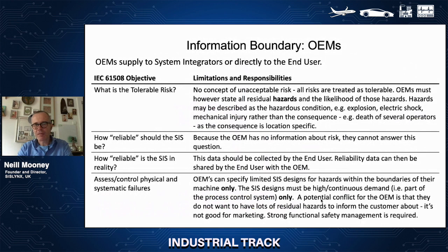An information boundary for an OEM. OEMs supply to system integrators or directly to end users. In terms of tolerable risk, there is no concept of unacceptable risk in the standards. All risks are treated as tolerable. OEMs must, however, state all residual hazards and the likelihood of those hazards. They can be described as the hazardous condition, e.g. explosion, electric shock, rather than a consequence, i.e. harm in terms of the death of operators.